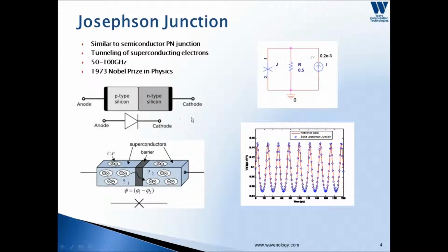You just use a p-type silicon and an n-type silicon and attach them together and apply a bias voltage across it. The phenomenon is that the electrons will only flow along a single direction. This is known as the p-n junction, and is even more well known as the diode. It formed the fundamental device for the semiconductor industry.